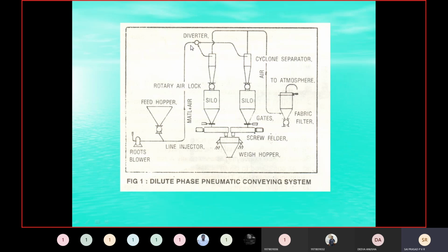This feed consisting of gas and solids comes from here, and immediately we keep a cyclone separator. A cyclone separator is a device used to separate solids from a gas on a continuous basis, so you do not stop the process. On a continuous basis the feed comes in, and tangentially we admit it. This diagram we will see in our fourth unit. It enters the cyclone separator and starts rotating. As it rotates, the material and the air are thrown out. The solids are the first to go out, away from the center, because they are in a rotating field.